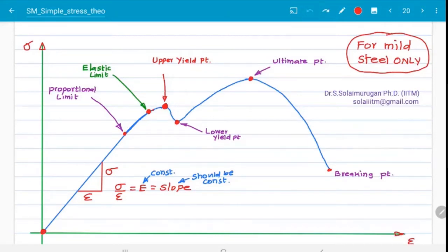So permanent plastic deformation will be formed. Just imagine, in any mechanical or civil engineering machines, if any mild steel component is deformed permanently, it cannot run peacefully inside the machine or the assembly. So whenever permanent plastic deformation is initiated, that point is assumed as the failure point.